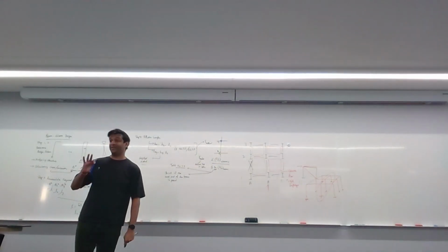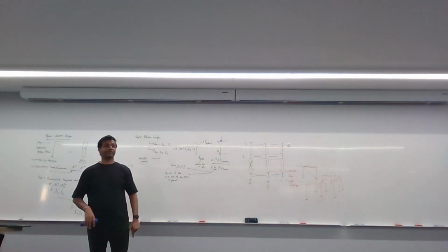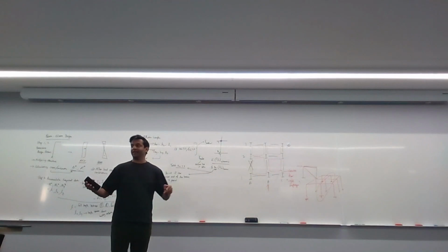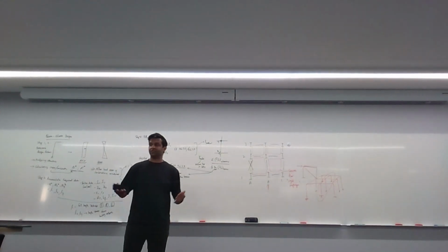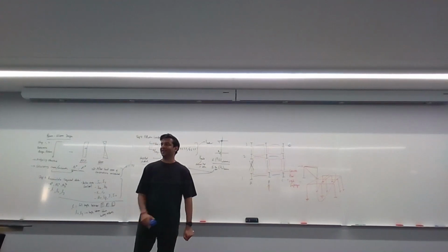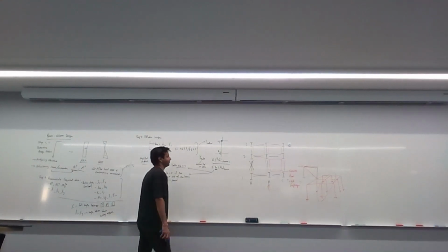Gamma. Again, I really recommend practicing the gamma method, because if you get a beam column question, 9 times out of 10, your effective length calculation is going to be a gamma method type calculation. Especially if you only have 2 questions in your exam.